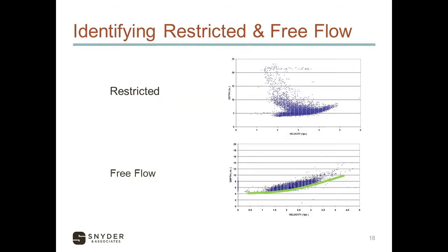This is an example of what we see from a flow monitoring equipment output. We're processing all this to actually quantify a flow, but this is what's being reported from the meter. We're getting a depth and velocity, and just wanting to give an example of how the data is considered valid versus invalid or needs to be cleaned up.